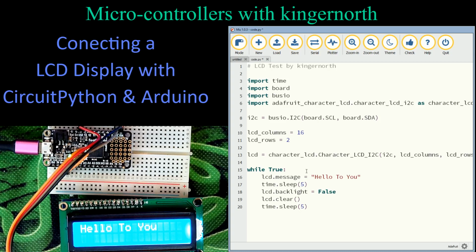So one thing I better do for when it goes through the loop here is I probably should come back up to the top here, and I should include LCD.backlight, and I should make sure that the screen is on when I first start. So there we are there. Now I've set it to true here, and I've set it to false there. If I save this, it's going to go onto my screen, so we'll be able to see it down there in the bottom left. Right away, I'm going to do it.